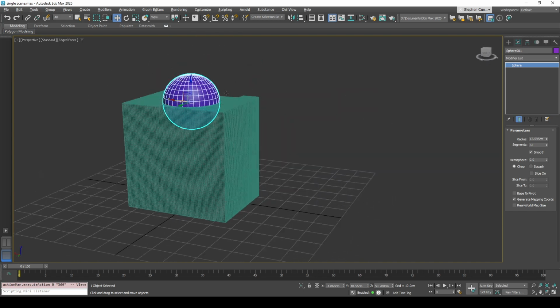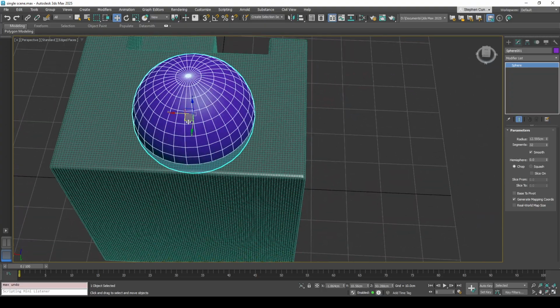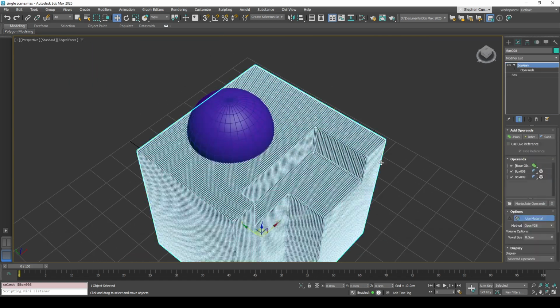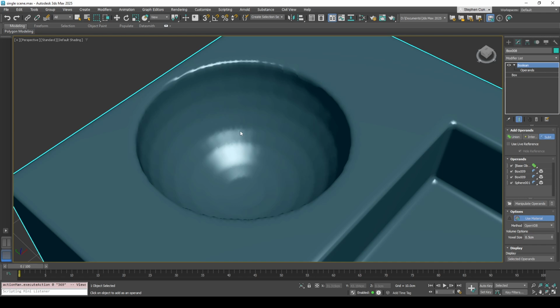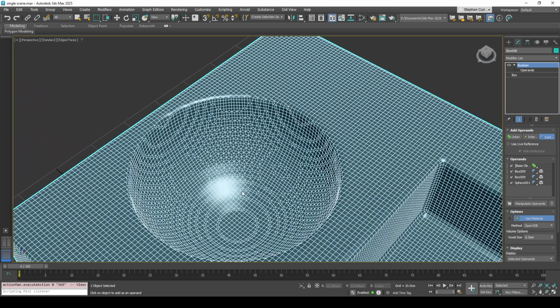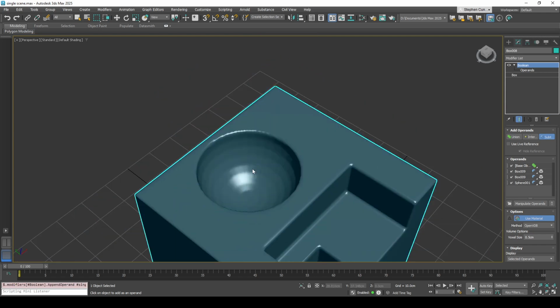So we'll have a look at the sphere, just being quite raw. So we'll do the sphere. Where do we want to put it? I don't know, we'll put it here. We'll do the sphere quite raw. So let's do a subtract, and you can see there where the low resolution on the sphere has caused some slight issues. It's actually modeled them in, so you can see it's attempted to model that area in. So what you would do is, if we just use Control Z, go back, I'm just going to click on the canvas to select out of here.